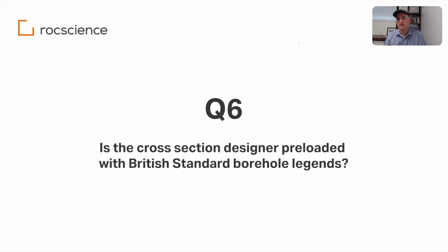The new version that came out last week allows you to upload your own hatch pattern. So now in the settings page, hatch design tab, there is a new tab called user defined hatch, and you can upload your own. You can design your own image, save it in PNG, and then just upload it.